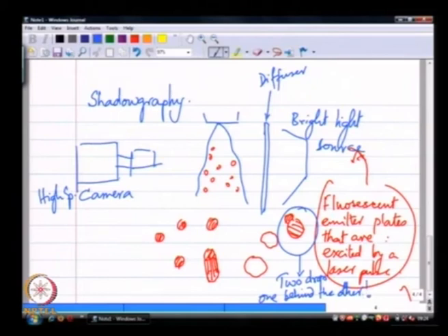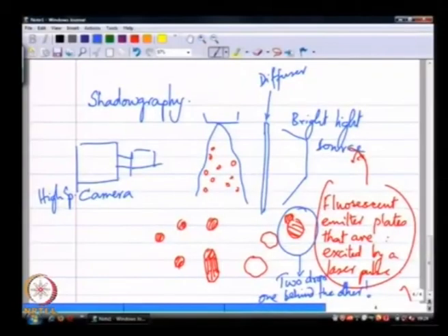Okay, and both these drops may still be within the depth of focus of my imaging optics. So, I can with my naked eye see that there are two separate drops, and I can use appropriate image analysis techniques. So, start with edge detection and look at sudden change in the gradients of the edge, and from there identify this composite image of two drops one behind the other as actually being two separate drops, and you can ascribe a size to each of the two drops.